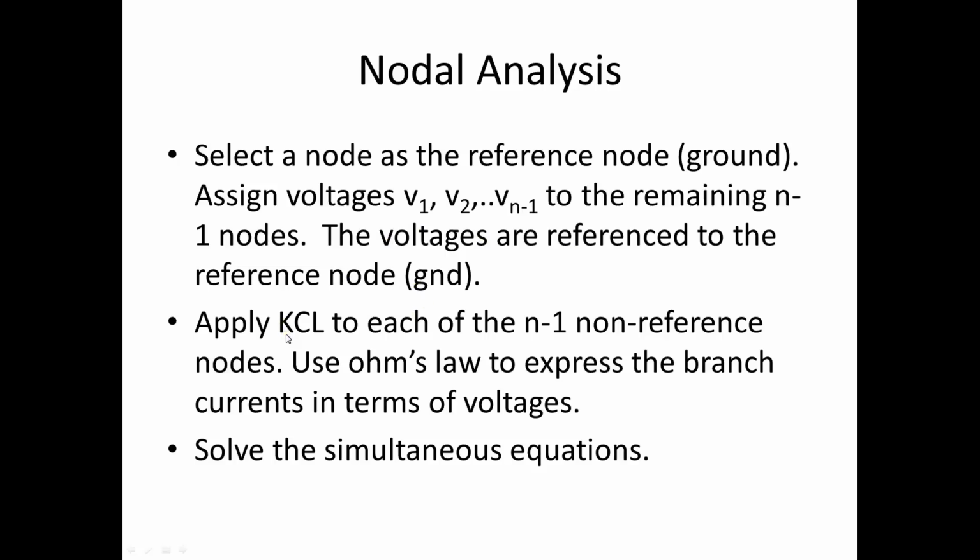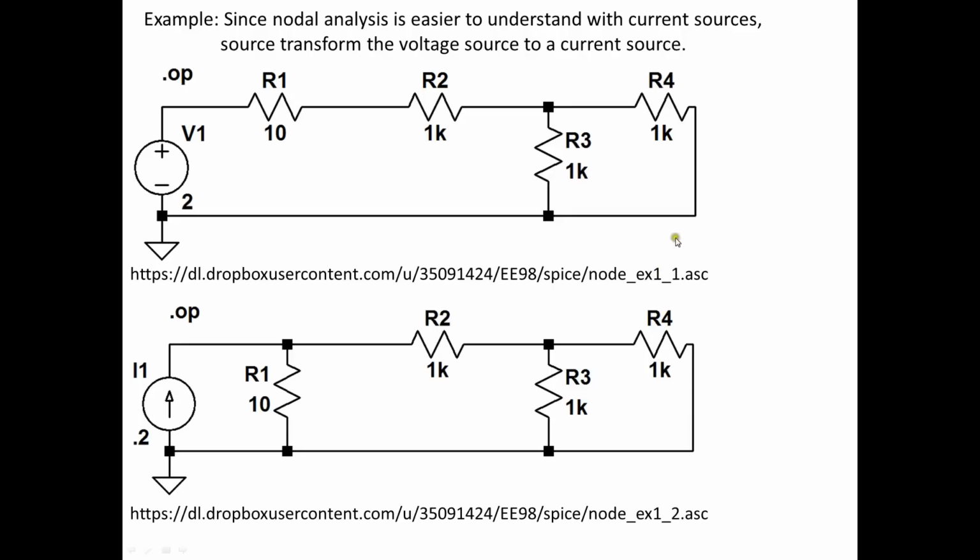We apply KCL to each one of these non-reference nodes, and we use Ohm's law to express the branch currents in terms of voltage. And after some simplification, we'll have some simultaneous equations that you can solve in general any way you would like. So let's take an example.